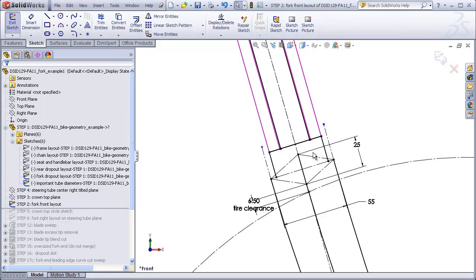In our case, we're actually making an oval shape that we're going to be controlling at 4 corners, but I don't want to draw the actual oval shape in this sketch because the true oval shape that will be swept needs to be drawn after the guide curves are completed and have Pierce relations to it. So this diamond shape here is just a placeholder to remind me of where the 4 corners of the oval are going to go.